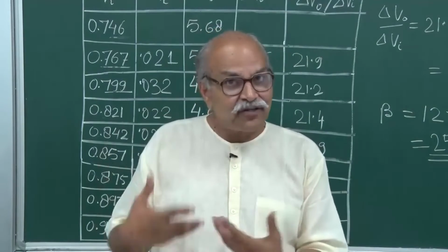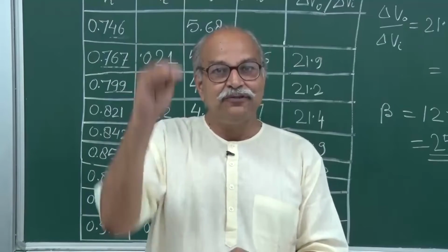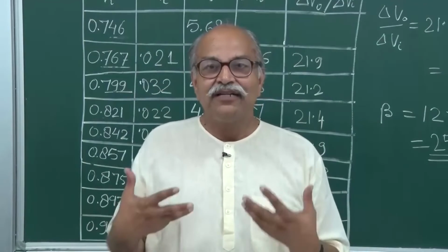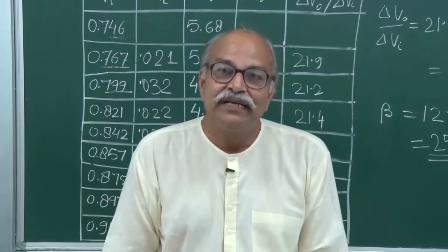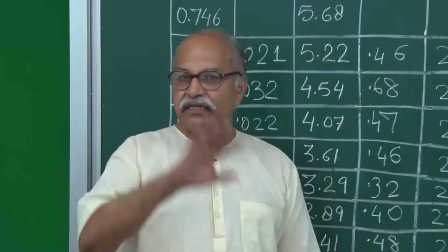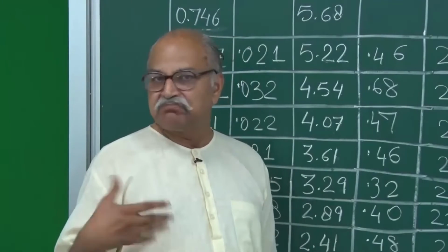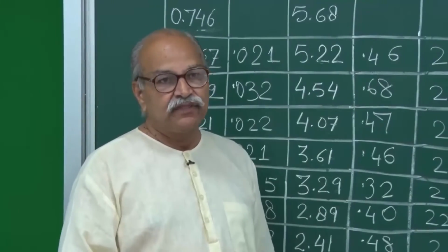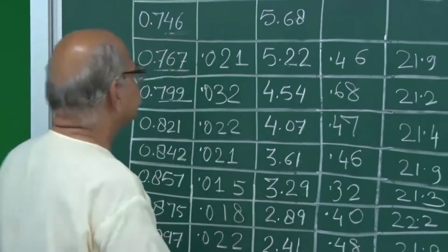And in digital electronics, the switching from high value to low value at a faster speed is very, very important, and all these things make the transistor a useful device for a switch. So the circuit of a transistor as a switch will be the same as this common emitter circuit that we had done. Let me draw it again.